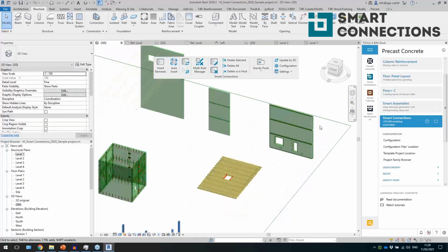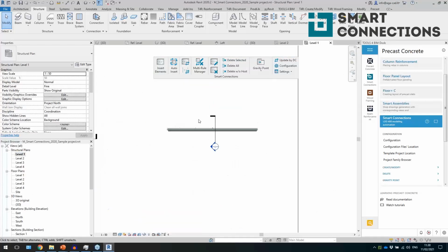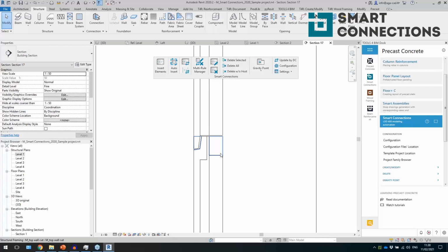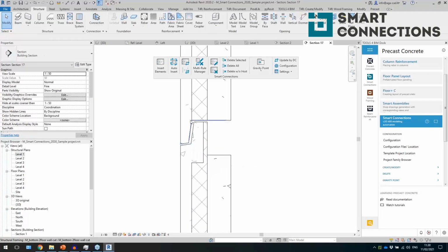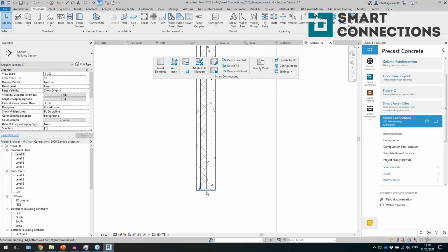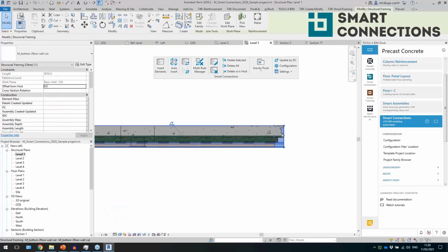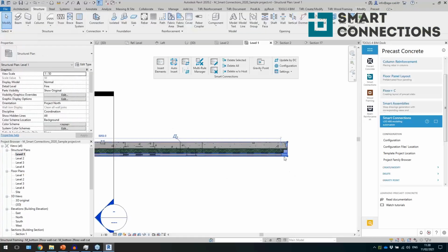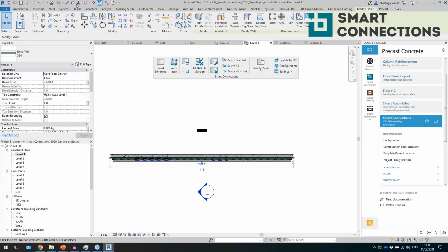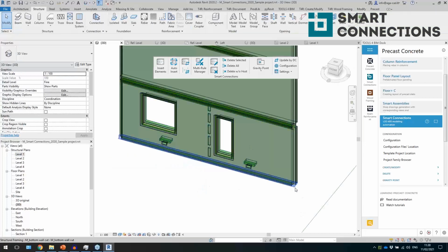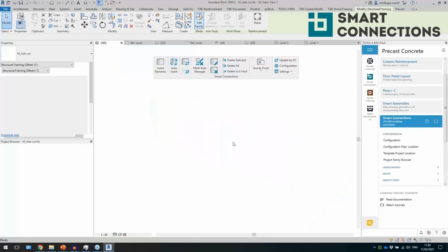Then other walls over here. These are like I was using line-based families to cut the top of the wall, then to place this kind of solid to get this kind of connection, or at the bottom I want to have this one, or at the ends I want to cut them in this kind of shape. So that's the way you build your families. Basically, you can get quite fancy shapes, not very typical for you, right?